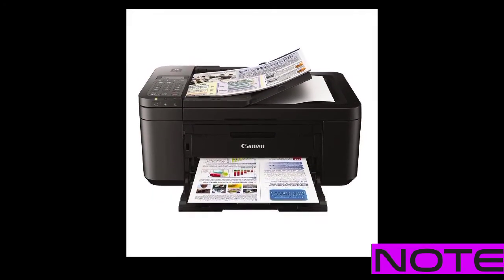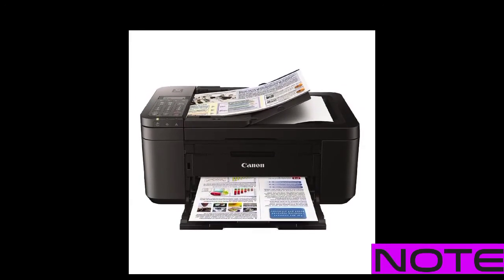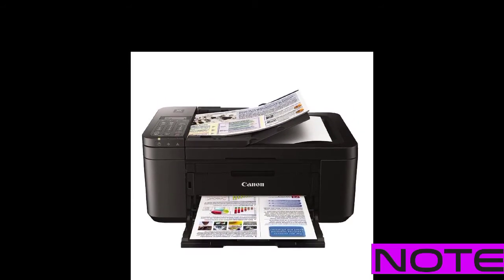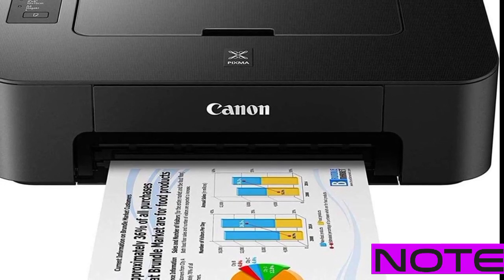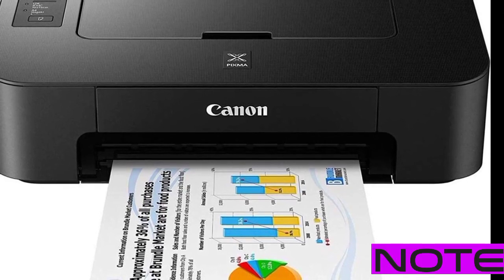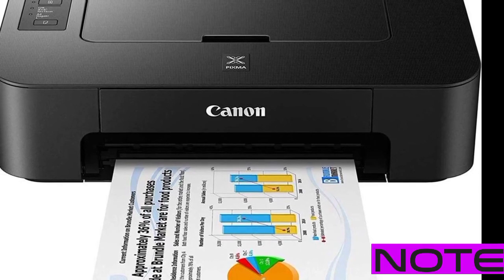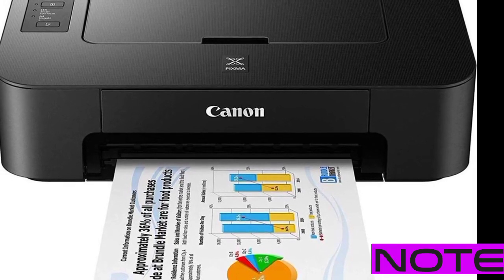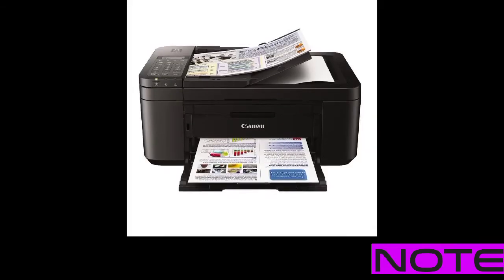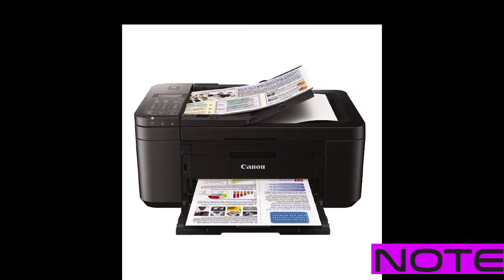Each nozzle can be heated up selectively in a few microseconds using the resistive heating effect. On heating, the ink in the ink tank of the ink cartridge expands and is ejected out from the nozzle onto paper. This ink drop forms a tiny dot of ink on the paper. As tiny dots of ink combine to produce a pattern, they can be used to print both photo quality images and characters of any shape and size. A high resolution inkjet printer can print even 2400 dots per inch.